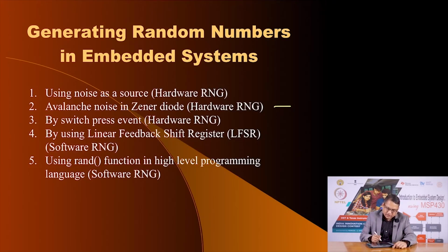You can use an interesting topology called a linear feedback shift register. We are going to dedicate a few slides to describing what a linear feedback shift register is. We are going to show a couple of experiments on how we can use an LFSR to generate pseudo random numbers, and at the end you can also use the built in random function that many embedded C compilers support.